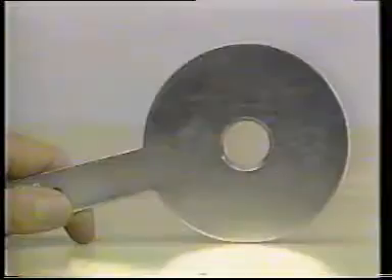Orifice plates are often provided with small vent holes, also called weep holes. The weep hole can be located either at the top or at the bottom of the plate. When used in a gas system that may contain some liquid, the weep hole is located at the bottom. For example, in a steam system, locating the weep hole at the bottom allows condensate to pass. When used in a liquid system that may contain gases, the weep hole is located at the top.